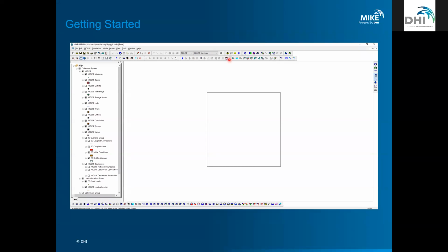It is that simple. You just direct where it is, and it'll load in the background. Then in the table of contents, it will show up, and you can check or uncheck it as needed. A recommendation I have, if it's a very intricate world imagery or something from satellite, is that when you're zooming to different parts of the network, I would turn the layer off to make it faster when you're moving around, and then turn it back on when you're in a very specific area.